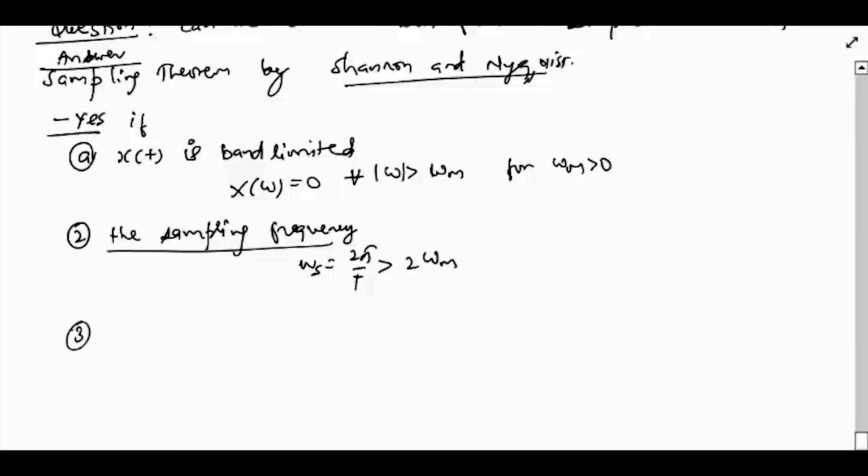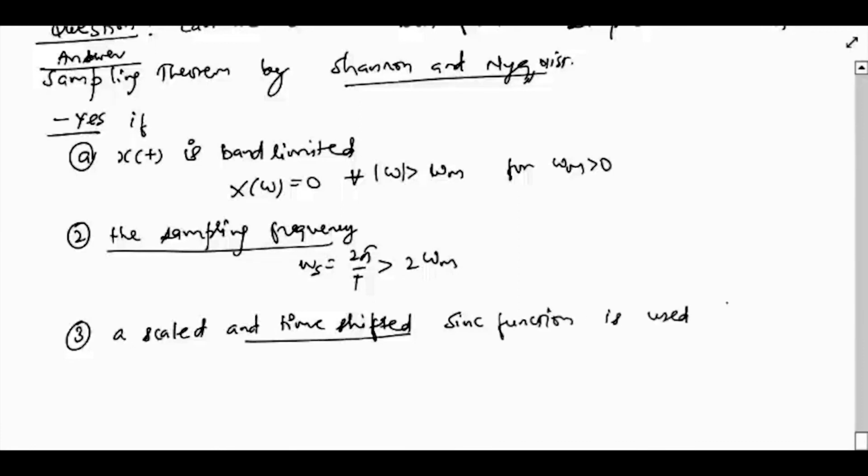And the third condition is a scaled and time shifted sinc function is being used for reconstruction, for interpolation. A scaled and a time shifted sinc function is used for interpolation.